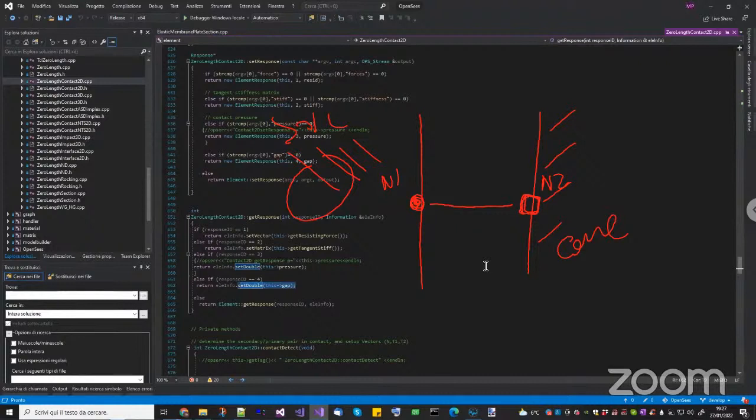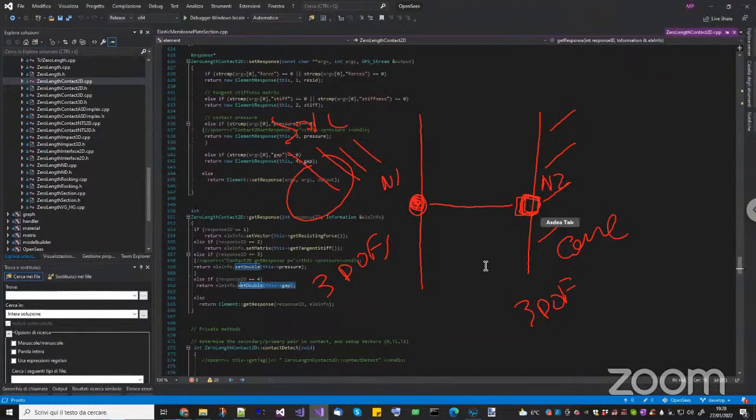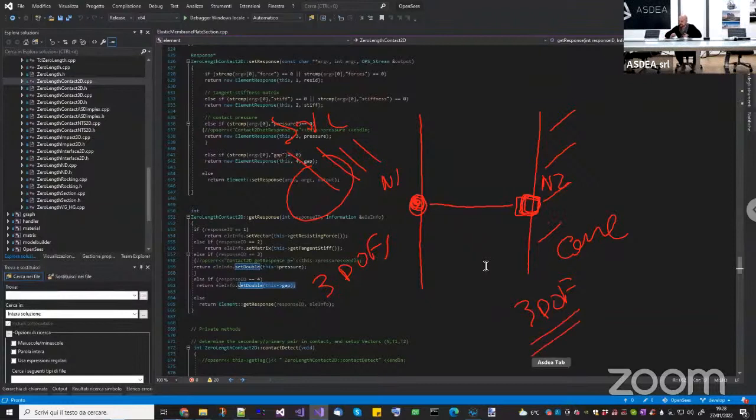No problem, but you have to take care of something. The zero length element, in STKO, this is done automatically. If you're doing it manually, it's different, because if you're using a simple U element for the soil, so a simple displacement element, then you have 3 DOFs. And this is fine. If you model the concrete with solid elements, you still have 3 DOFs, so you can create a zero length that connects node 1 directly to node 2.